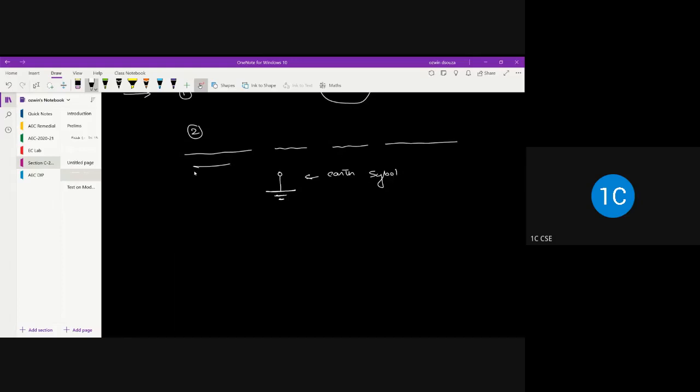Okay, so your wall socket, right? In your wall socket also you have line, neutral, and earth, right? So internally, this particular earth socket is connected to the earth pit. So if there is any current leakage, the current will flow through the earth. That's because this particular resistance is kept somewhere between 5 to 10 ohms, which is very, very small in comparison to human body resistance.